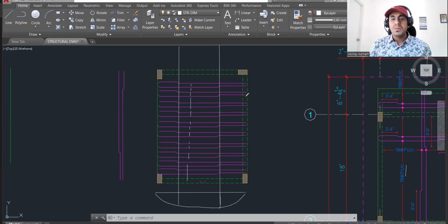moment because of this beam and the slab junction. See, this is actually the bending moment diagram of your slab. But due to the beam, what will happen? You get a negative bending moment. That means if I draw that here, you'll be having a negative bending moment, then you'll get a positive bending moment, then again a negative bending moment. So this is negative, this is positive, that is sagging, and negative.